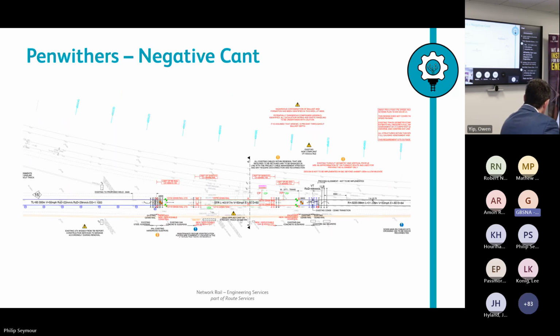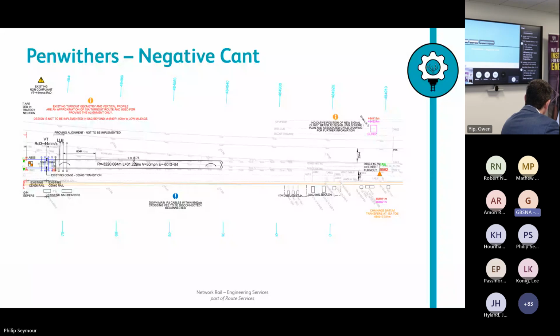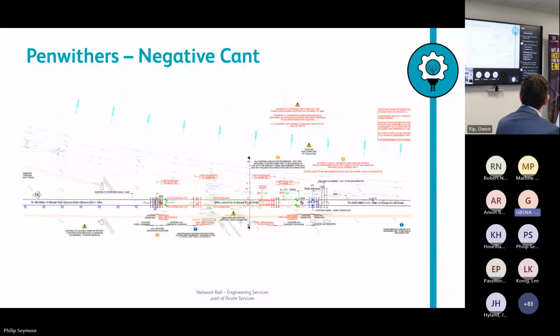The reason for having to do this is to supply construction services with 3D centre lines and rails for setting out purposes and excavation files. This is business as usual for us. Historically, you'd have to create a fake cant rail, adjust it vertically, and try to get everything about right. So, being brave and industry leading, we decided to use this as an opportunity to start learning OpenRail Designer in the real world, live. OpenRail Designer is used for 2023. Kavans, one of the product managers, has introduced something called Force Positive, which enables you to change the cant rotation from inside the rail to outside the rail.